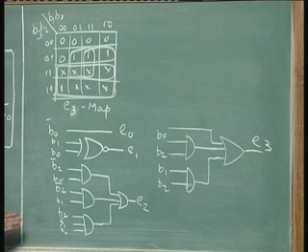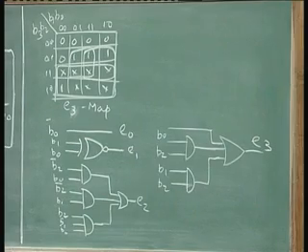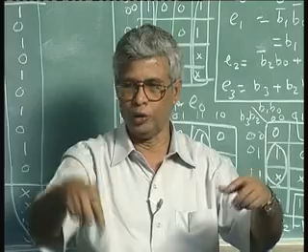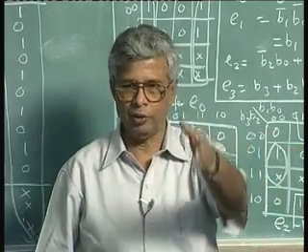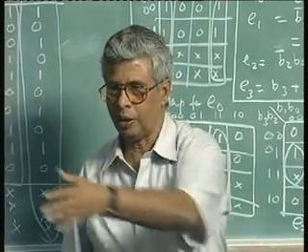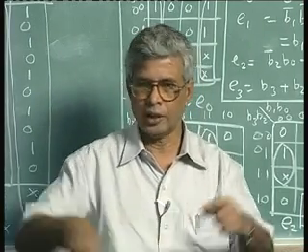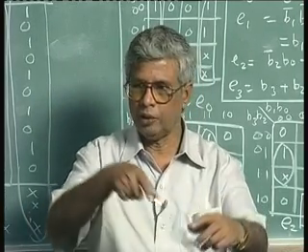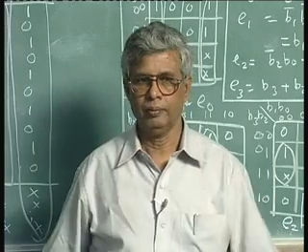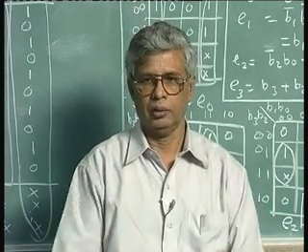You represent it like this, a solid, when you wire it up, of course. There is B0, B1, B2, B3 coming into a circuit and you have to get them inverted if you want: B0 bar, B1 bar, B2 bar, B3 bar. So, you will have B0, B0 bar, B1, B1 bar, B2, B2 bar, B3, B3 bar. Then you have all these gates, wire them up, crisscross and then get E0, E1, E2, E3. Then the circuit is built.